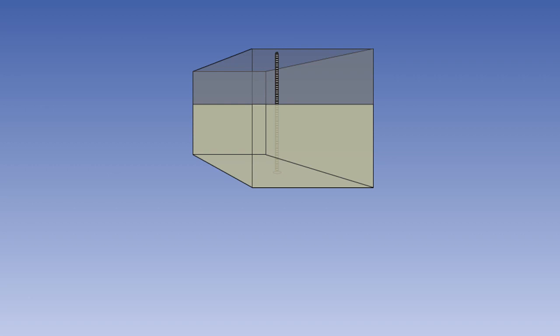Another method is the dripstick. This is a calibrated hollow tube which is withdrawn from the undersurface of the tank through a fuel-proof aperture. When the top of the tube becomes lower than the fuel level, the fuel will drip through the tube, hence the name dripstick. The volume of the fuel in the tank can be established by reference to the calibrations on the tube. The disadvantage of this system is that the user's armpit soon becomes saturated with the fuel dripping from the pipe.